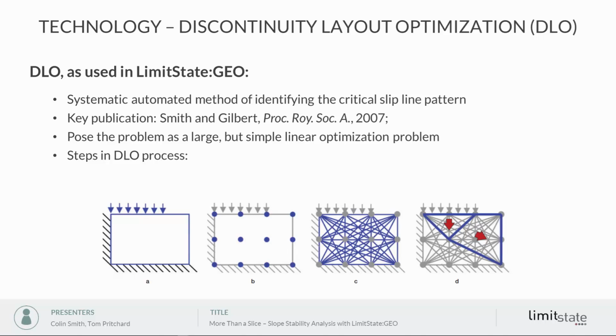But we can use far more than 12 nodes. We can use 1,000 nodes or 10,000 nodes and get a much richer set of potential slip lines, and that is essentially how the software works. And so it's not restricted to any particular pattern of failure. It can connect these slip lines up in any pattern that it likes to give us the critical mechanism.